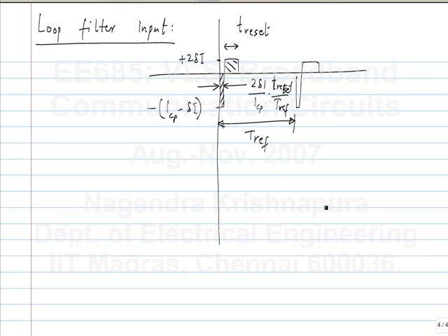Okay. So, how much will this reference feed through be compared to that in the type 1 PLL? It will be of the same magnitude. Let's say the bandwidth and all that is the same. Let's say the loop filter, we can't say the same loop filter because there is no loop filter in that case. So, what do you guess?